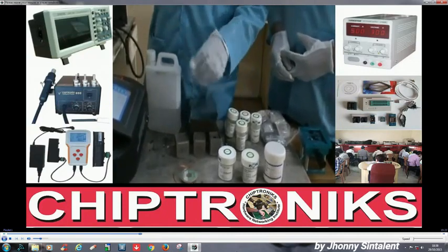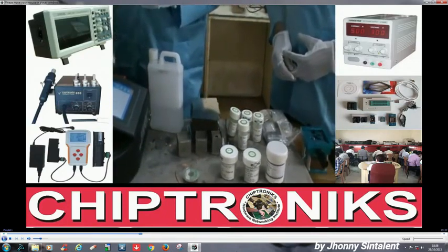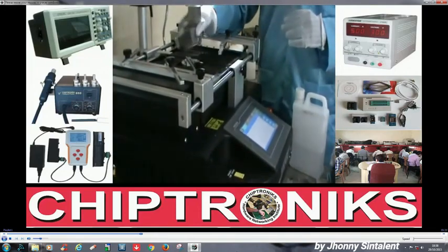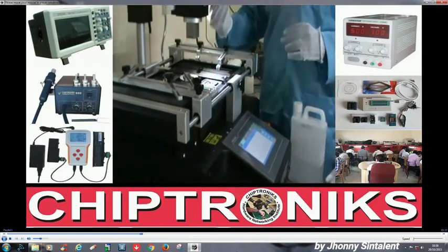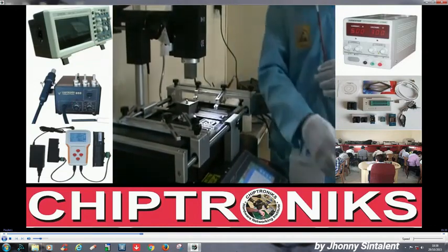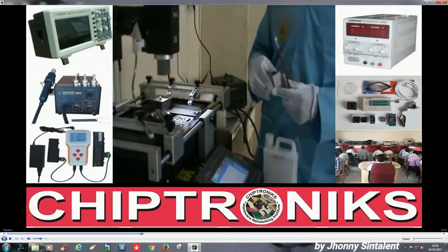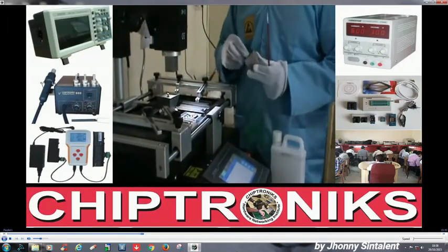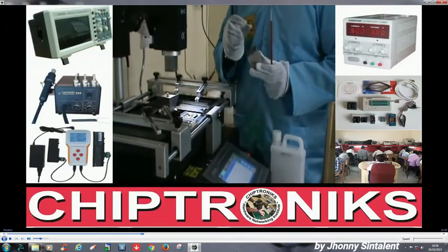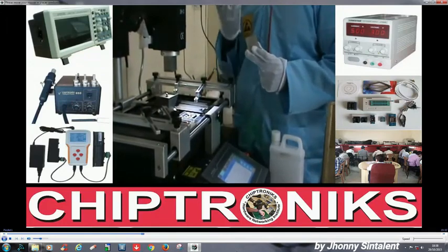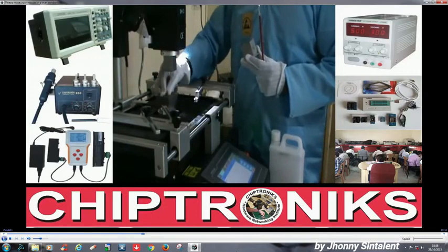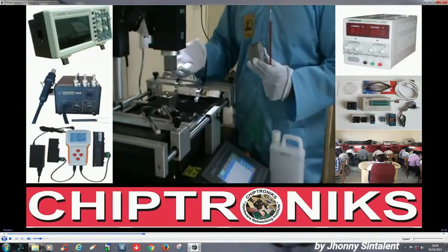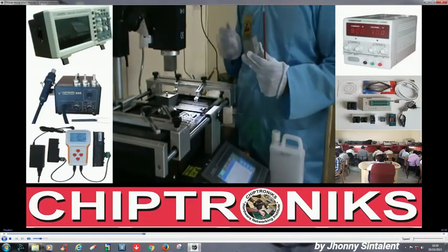And this machine will have various types of nozzles according to the type of BGA chip we are trying to remove. You can see these are removable. There are basically 5 types of nozzles, 2 for the bottom. You can see there is a hole inside this nozzle to support air flow, right? And it has a supporter over here, because this supporter will give support to the PCB from the bottom side.